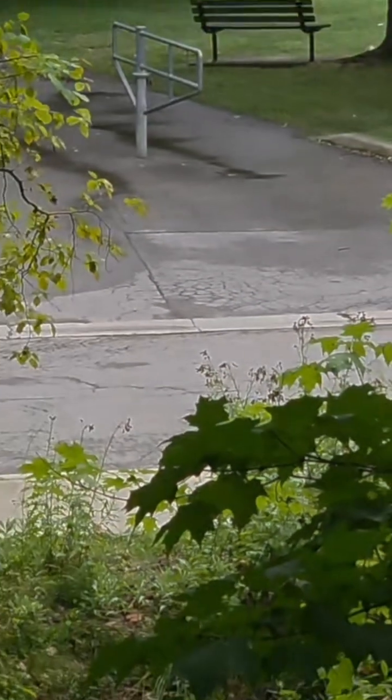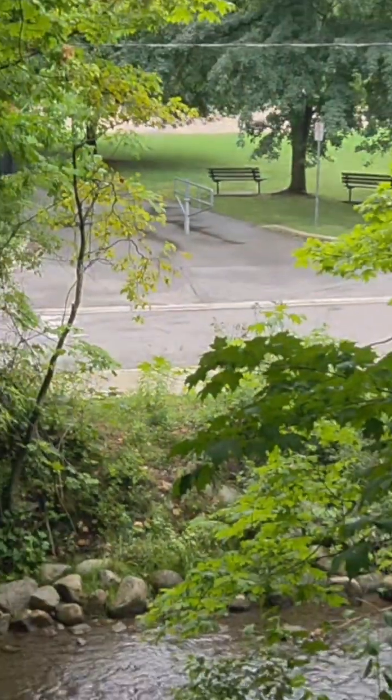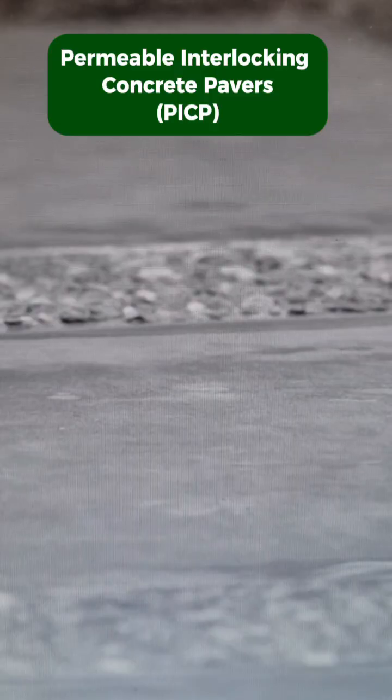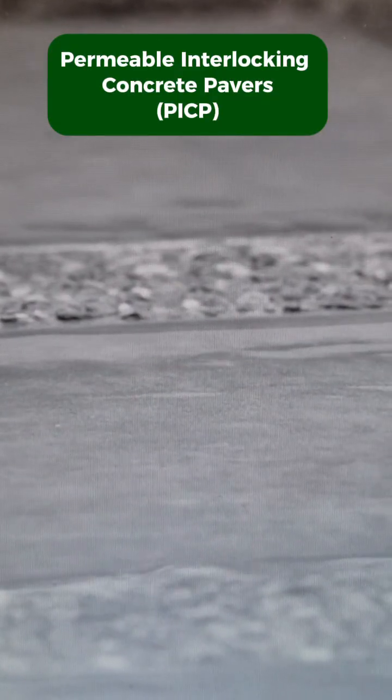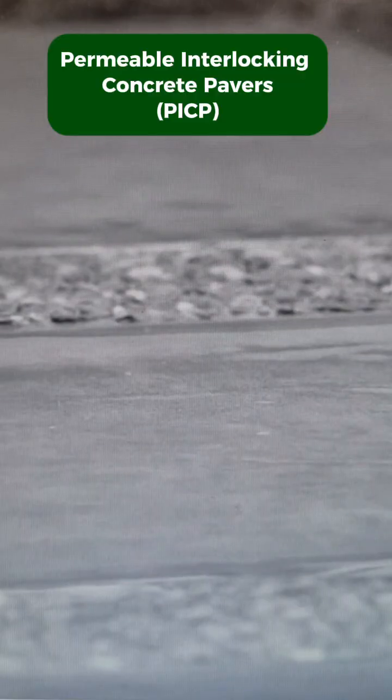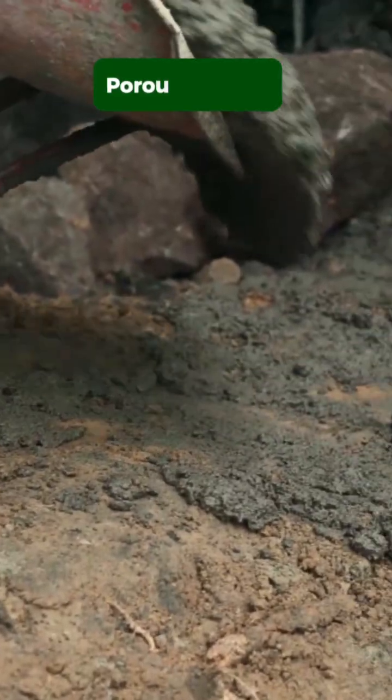Fortunately, engineers have developed several alternatives that allow rainwater to pass through the surface instead of flowing away. One option is permeable interlocking concrete pavers. These concrete blocks have small gaps filled with stone or gravel, allowing water to drain between the pavers while still supporting vehicles and pedestrians. Another solution is porous asphalt.